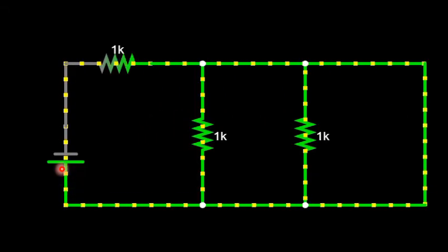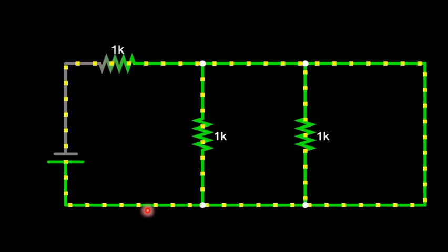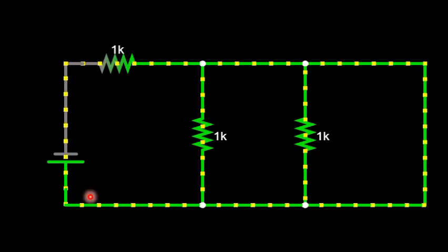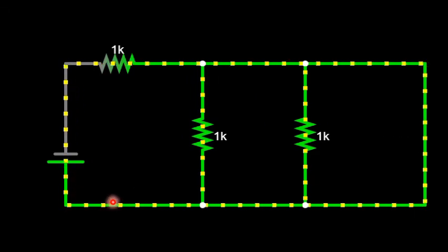So we have a circuit here. You see that it started moving. The yellow arrows going is the current. You see that nothing really moves on these two resistors. That means they've been short circuited. Look at it. It moves all the way here to here and back, because there's nothing going through them. If there was current passing through, you would have seen these yellow lines moving down, but it tells you that no current is going through them, nothing. They've been short circuited and they are just there.